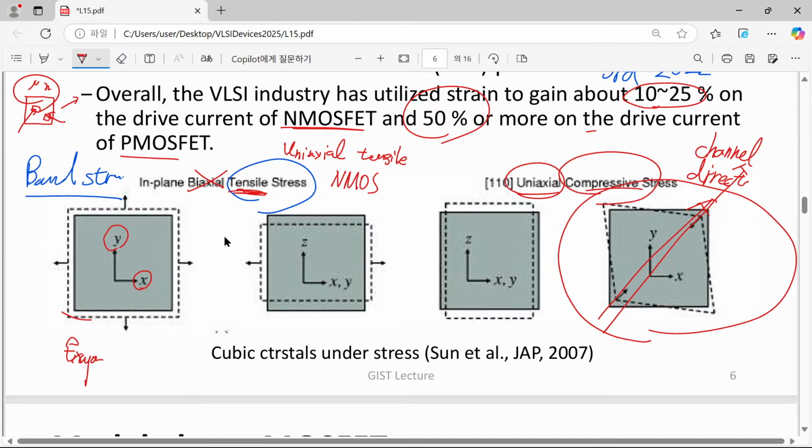So nowadays, the mismatch between NMOSFET on current and PMOSFET on current is not that high, not like a factor of 2 or 3 taught in our circuit design books. Usually, maybe it is really comparable, just several 10% difference in their own current.